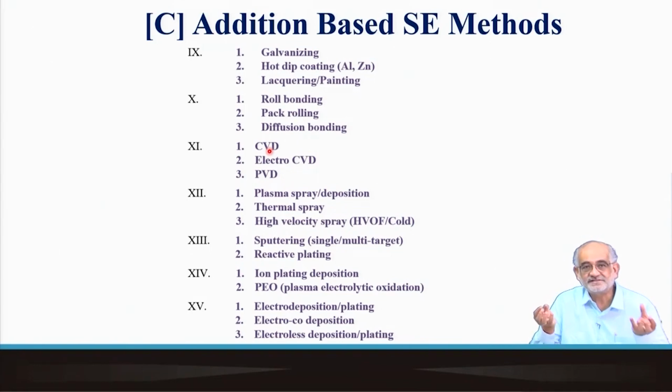So I take species into the vapor state and make them react in the vapor state in presence of a very active surface, which acts as a catalyst. So the species in the vapor state react and form a diamond-like coating, let's say. You create basically a carbon coating which will have a combination of sp3 and sp2 bonding, and then you get a very wear resistant coating and also several other good functional properties are imbibed.